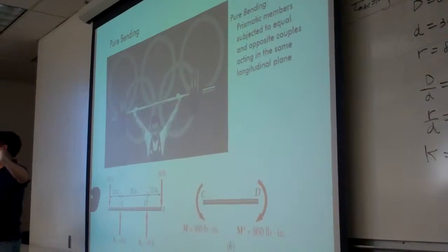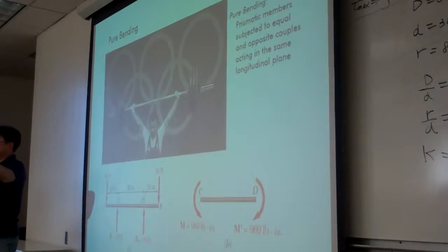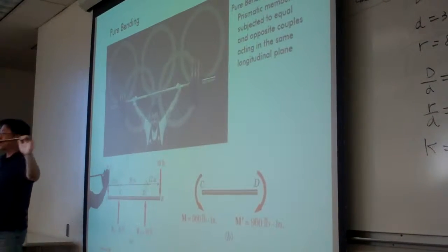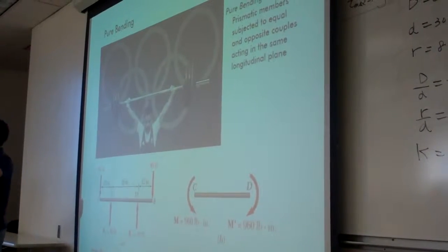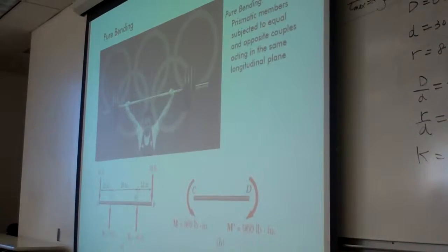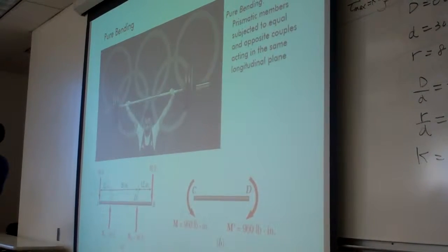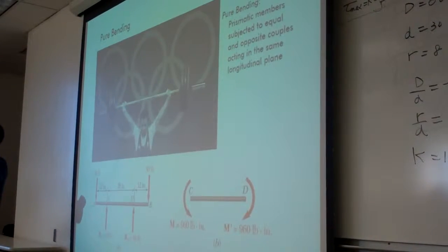Bending, the loading is like this. Okay, bend over. And in particular, in chapter 4 we talk about pure bending. Pure bending means that in a certain portion of a structure, the bending reaction at every single cross-section is constant. This is called pure bending.